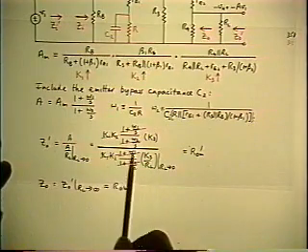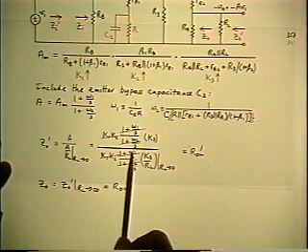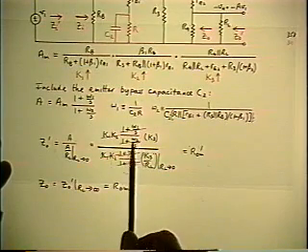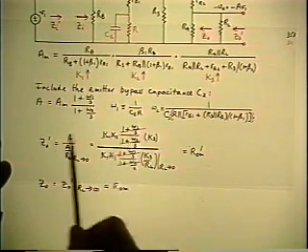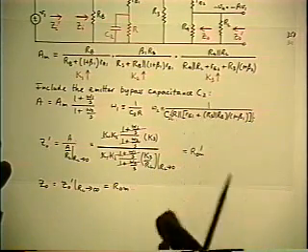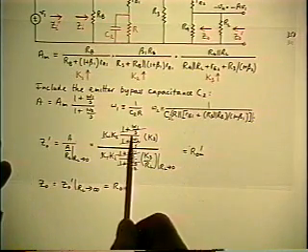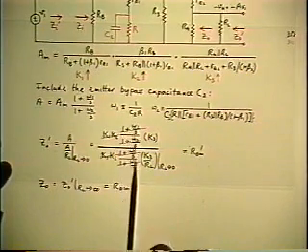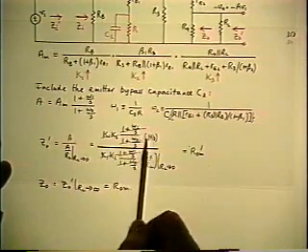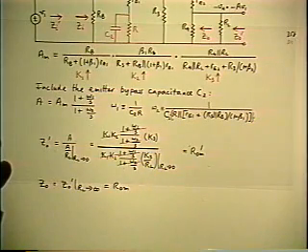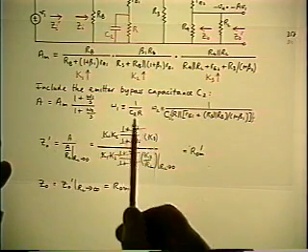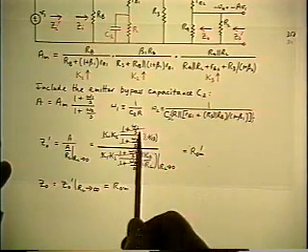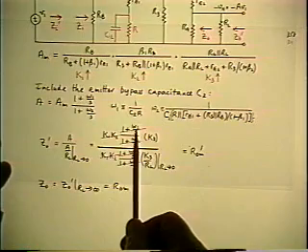Now, the only additional thing is we have a pole and a 0 as well, but they are just additional factors. And the same consideration applies to those as to the K1, K2, K3. They're just factors of A. Therefore, any factor of A not containing RL is unaffected by the limit and cancels out, and that applies to corner frequencies as well. So when you look at the 0, it doesn't have RL in it, so it cancels. Not only the corner itself, but the entire factor.